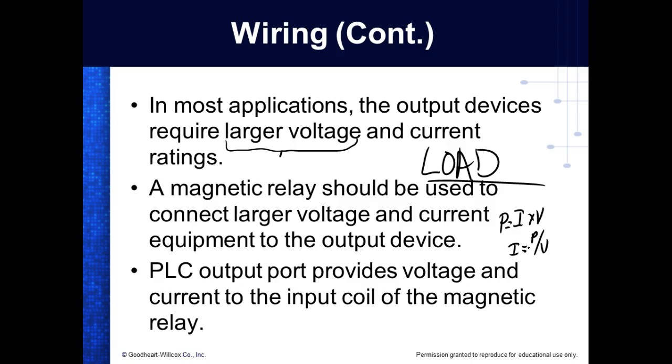What are resistors rated in? What's the two things resistors are rated in? Well, three. What's the three things resistors are rated in? Size. Now, when you say size, you've got to be careful, because I could have a real big resistor that's rated at 1 ohm, right? So the ohm value, or the resistance. What else are they rated in? Wattage. How much wattage they can dissipate before they burn up, right? And what's the third thing? It's rated in tolerance, right?